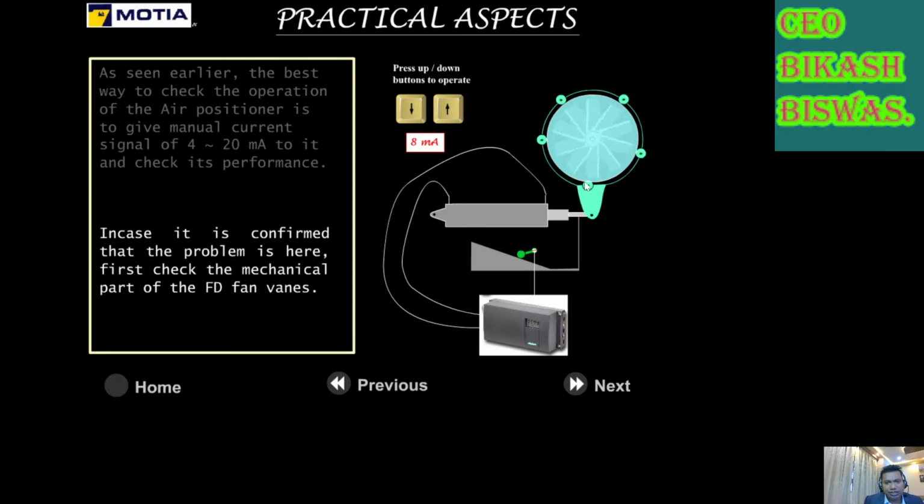Sometimes, due to wear and tear, there is a gap inside the linkage, or dirt and dust go inside, and due to misalignment and vibration, it gets stuck. This linkage gets stuck due to misalignment. So you have to free those parts, lubricate properly and make them free.